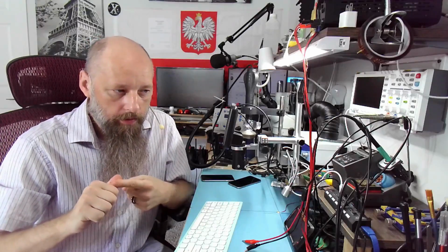The majority of faults on any kind of device, be it a computer, laptop, motherboard, or power supply, will revolve around power. And oftentimes, the reason the power is not being delivered is because of MOSFETs. MOSFETs either are not being controlled correctly, the control circuit is damaged or faulty, or the MOSFET itself is faulty. The main reason for that is because, in any kind of circuit, we want to use the cheapest part possible.